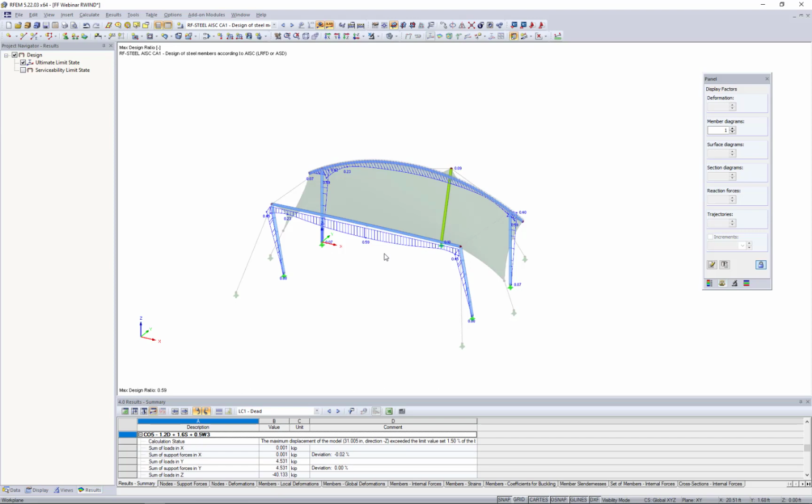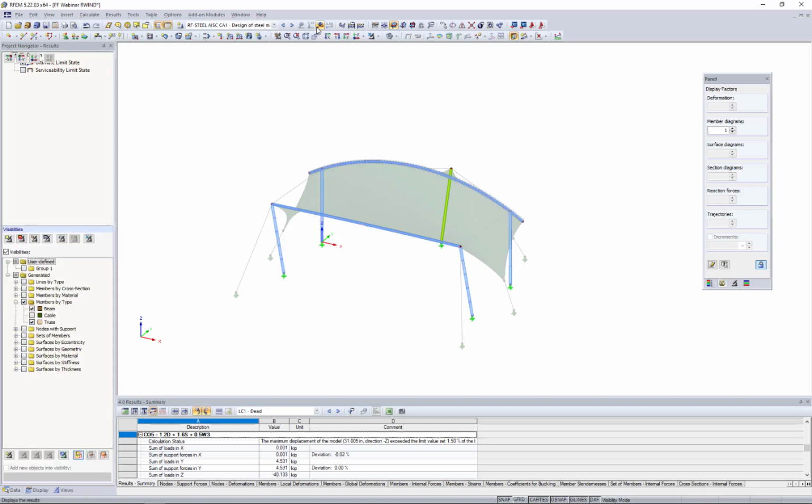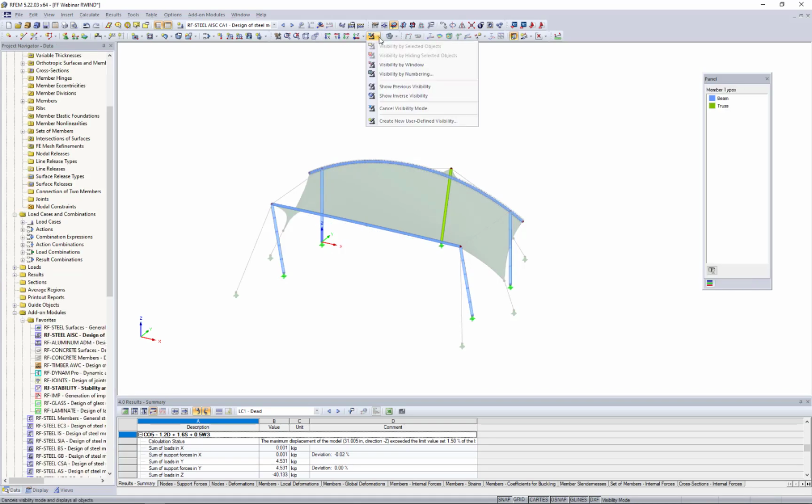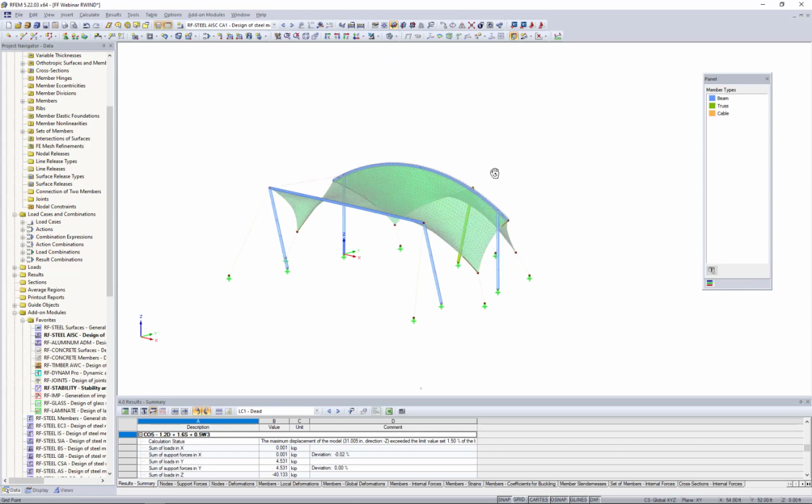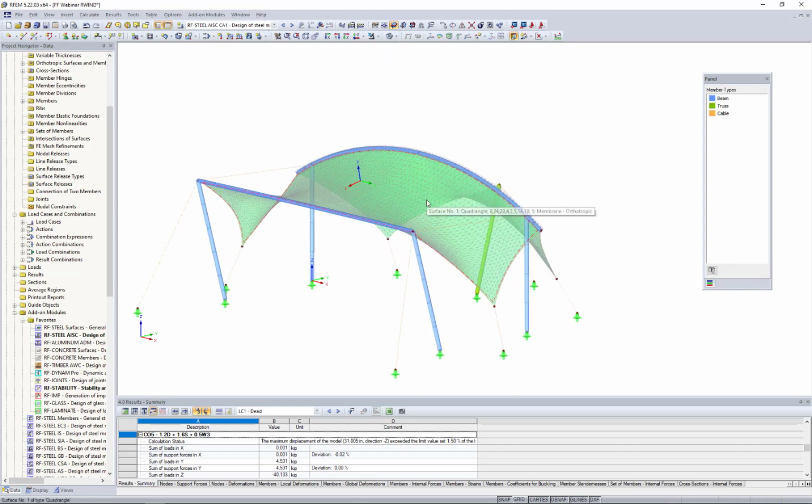The final thing that I want to cover, which will just take a couple of minutes, is the influence of additional structural bodies or structures in general and how that plays a role with our wind loads. So let's assume, for example, our structure today is, again, some type of tent covering structure here, and we want to use it to cover a seating area. So I'm interested, if I place that seating area underneath my tent or my canopy here, how will that impact my wind loads? Because it could be pretty significant.